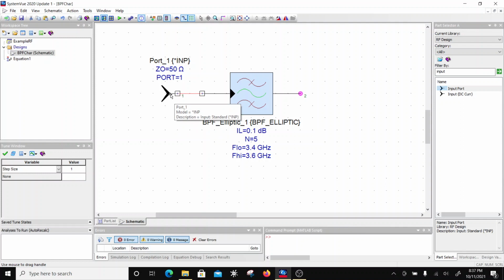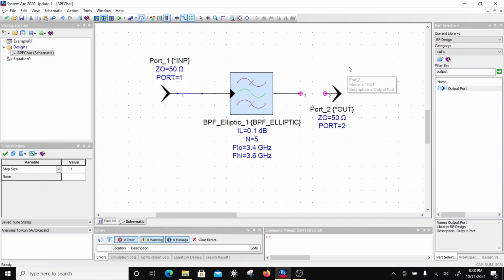They act as a signal source at this design level, but as soon as you take it to a higher level and insert it down in the hierarchy as a component, then these pins start acting as your 50 ohm ports. So there are two functions of these pins. Let's look at the output port here, and connect it. The schematic is now complete.